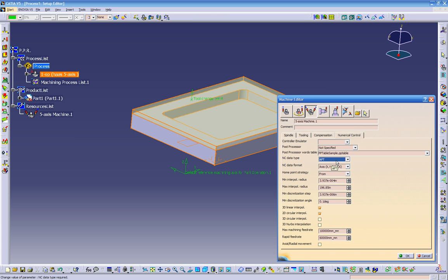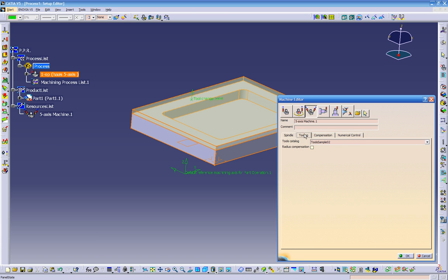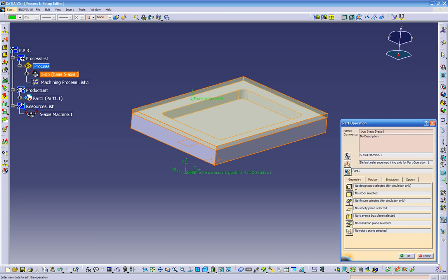And if you have a Haas machine, there are companies out there that will take the APT and convert it into NC or whatever your machine can read. So for now, we're gonna just create APT only. Okay. So once we set all this, we're gonna click OK. So we just get out of here, out of our machine.